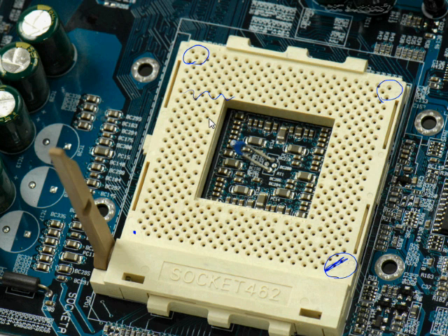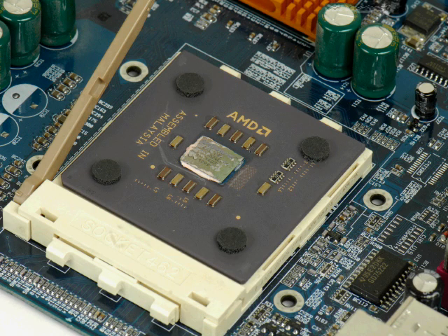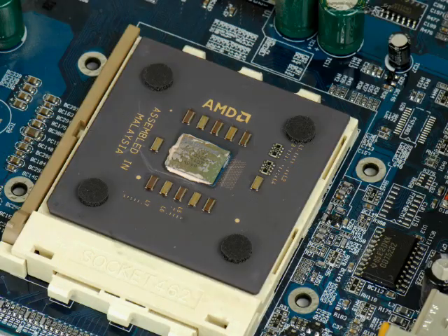Gravity alone will cause it to plop into place. Once that's taken place, you'll see the processor, in this example, is laying down flat on this. Then you'll take this little lever and lock it down here, and you'll see that it's then locked into place and applies pressure. It actually has a kind of a grid where those pins go, and this lever will move that whole platform into place and put tension on those pins when this processor is installed properly.